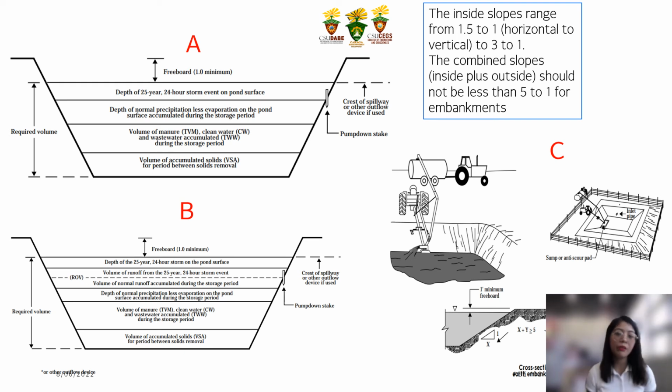The method of removing solids should also be designed for the storage ponds. If the waste will be pumped, adequate access must be provided to thoroughly agitate the contents of the pond. A ramp should have a slope of 8 to 1 or flatter, and be wide enough to provide maneuvering